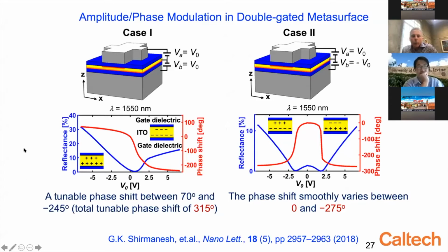You could also, for example, build devices that have dual gates. This is very much like a dual gated transistor in which you apply a voltage between the body of the device and the gate, and the body of the device and the substrate, or in our case, the reflective ground plane. The result is that you get 2 regions where the free carrier index is modulated, one right under the gate and one right at the back surface of this device.